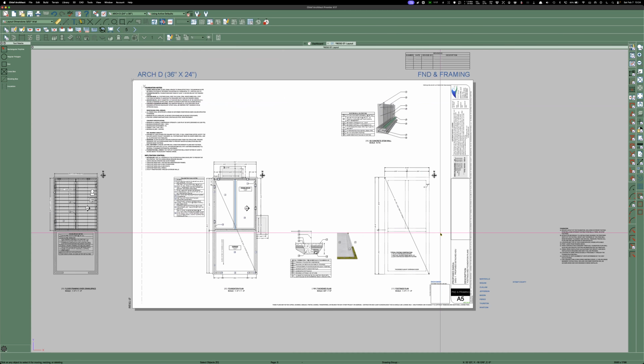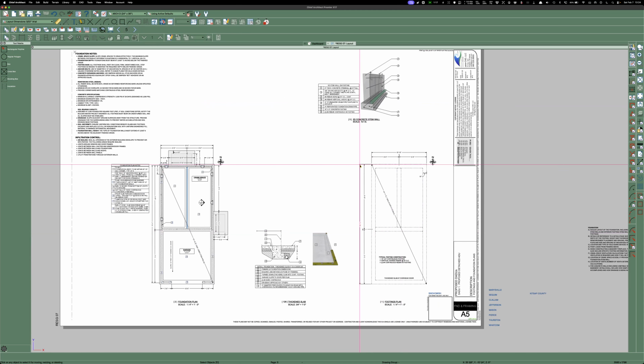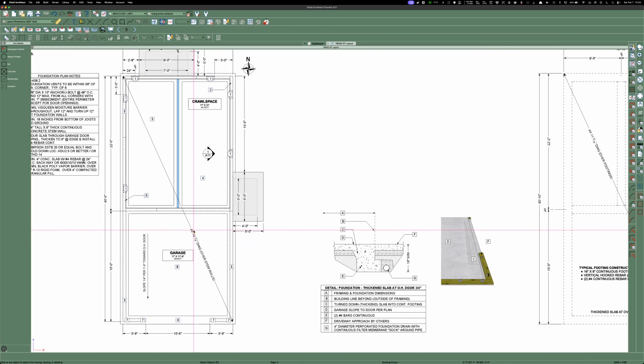So here we go. I like to do a footing plan sometimes. It depends on if they can monopour this. It's a little harder to do, but there are concrete guys that'll do it. But I'll throw in a diagonal just so that good framers and good concrete guys will always pull out their own calculator and calculate your measurements to make sure. So don't just trust me. But since I've already drawn it to the exact sizes, 18 by 40, it's easy enough to let the software give you this length. I don't type this in. I just pull the dimension, and that's what it is.